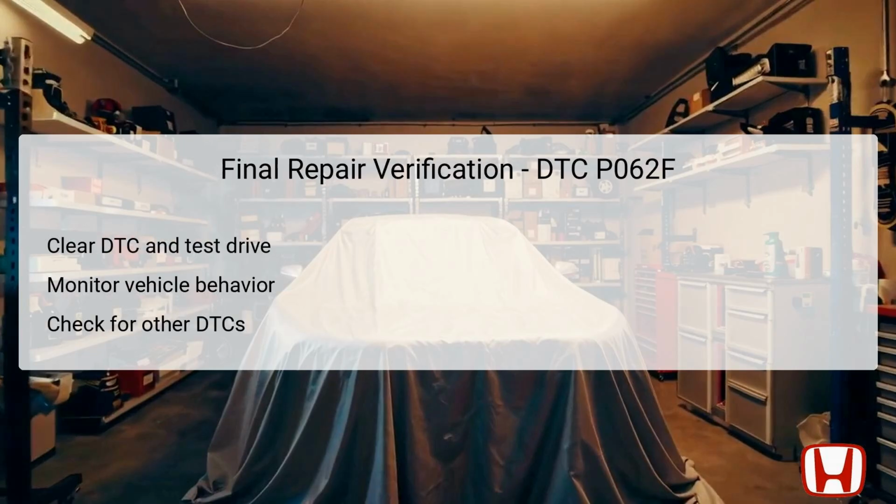The final repair verification process is critical to confirm whether the previously implemented troubleshooting measures have resolved the issue indicated by DTC P062F. Begin by clearing the DTC once again using the HDS, followed by taking the vehicle for a test drive. Observing the vehicle's behavior during various operational conditions is crucial. It helps in assessing the success of the repair.